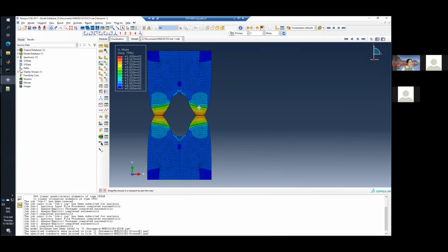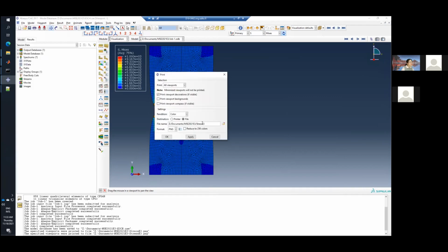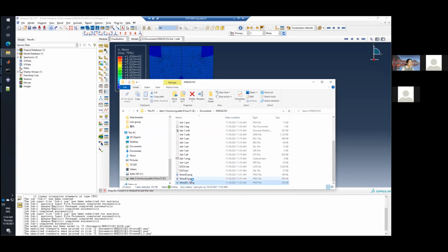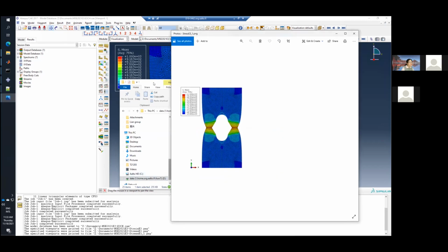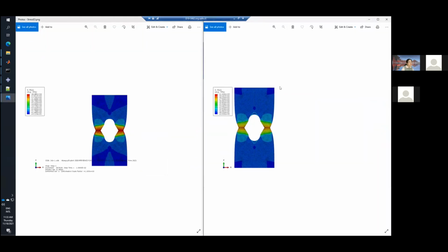So that's okay for all your 3 figures. You can zoom in or zoom out to make a proper size of it. Then you can print it again. If we see these 2 different, so there's a new one. Rename it as 1, and then OK. And if you compare these 2 figures, you will see this one will be a more professional one to show in your papers or in your report. So that's a slight change on the layout of how to save this figure or how to make your figure more proper.